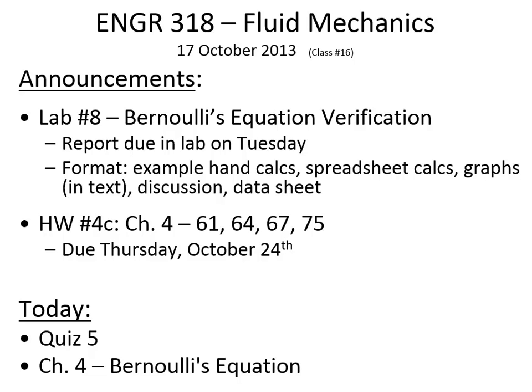And so you're going to be comparing the theoretical Bernoulli's equation, which we're talking about in class today, with the measurements that you take. So comparing how the pressure change is actually observed versus how the pressure change is predicted by what Bernoulli's equation would say. So do some example hand calculations. For the rest of the runs, though, you can do it on the spreadsheet.